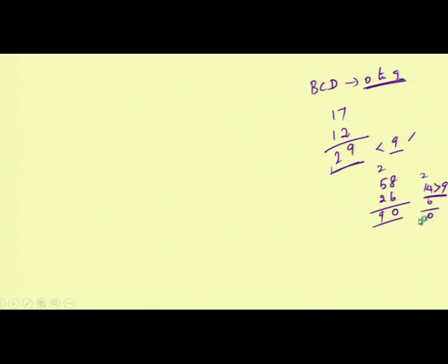So, for this kind of addition, what are the facilities in the 8051 microcontroller? Just like that, you have to initialize one of the data in the accumulator. So, MOV A, #58, right. Another data you can use in any one of the registers. Suppose I am taking MOV R1, #26.